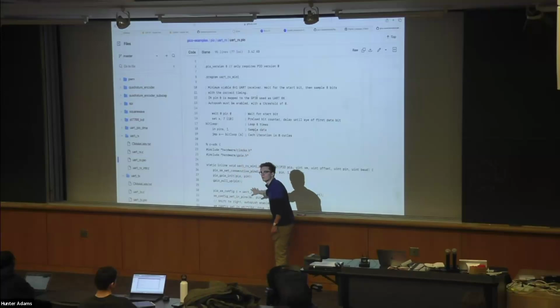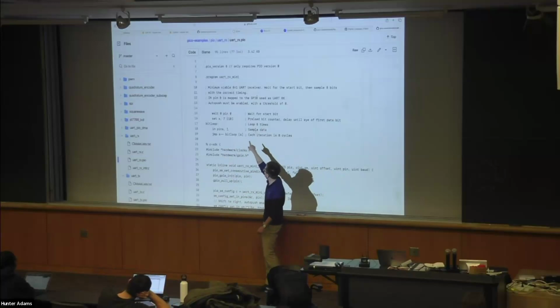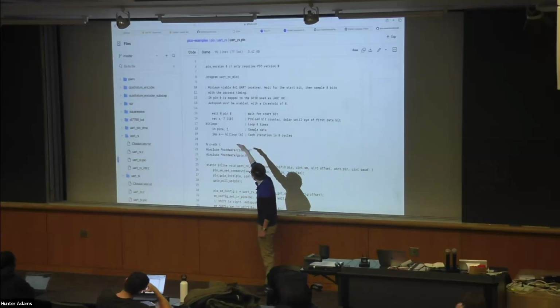And we will have mapped which pin we're talking about down here. We might have multiple pins up there. So pin 0 is, of course, our RX line. We've configured it such that it's the RX line. So we'll stall on this instruction for as long as our RX line stays high. The moment it drops low, we pass through that.